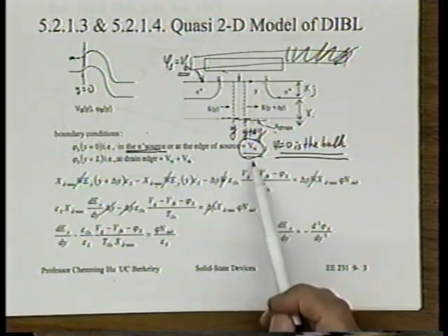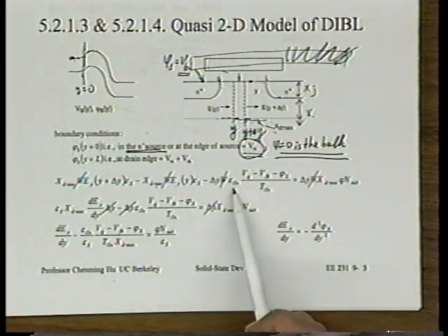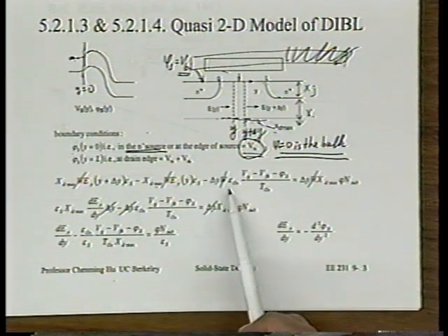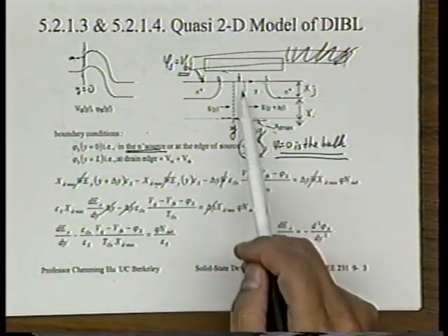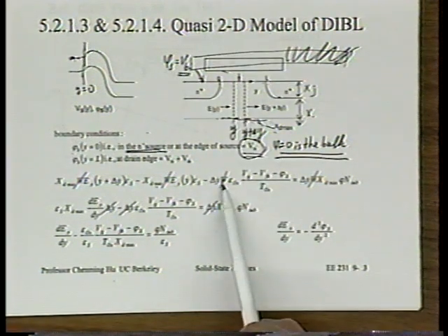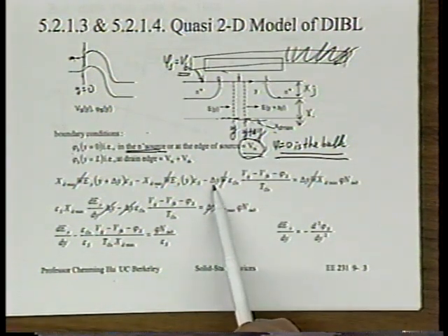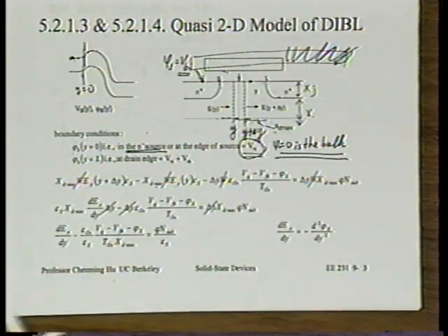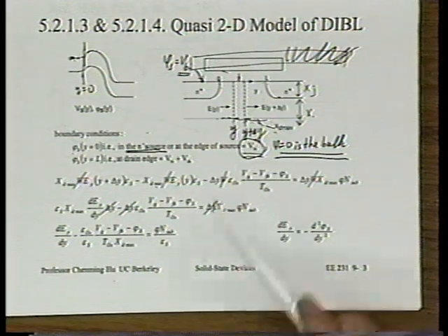All right, so this is the electric field in the oxide. Multiplied by the oxide epsilon, that gives us electric flux. Is that right? And times the area of that boundary of the Gauss box, which is W and delta Y. Do you see where delta Y comes from? Delta Y is this dimension. W times delta Y, do you see that's the area of that surface of the Gauss box? Any questions? Excellent.